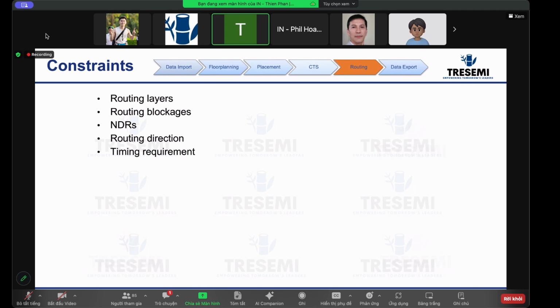So and then once in a while we have a special net, or very sensitive net, right? So probably similar to the clock net, but in this case, it's a signal net that we know we have to take care of, give it special attention. Then we can create an NDR for it, right?